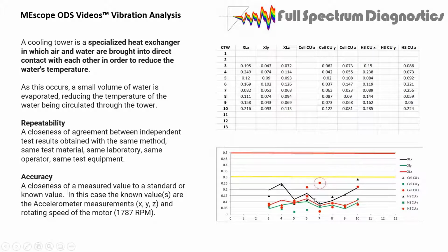I was comparing the trends, because even though somebody else takes over your route for a week because you're on vacation and they put the transducer on the machine, but not in the spot you usually put it because they don't know, the trends get screwed up. Same sort of thing can happen here in that if I select a point on the housing that I would normally put the transducer in, that should match the data from the transducer. And I tried to make that happen, and it's close. As you can see through here, all these triangles line up with the axial direction. The circles line up with the Z direction, and the Y direction is in green.